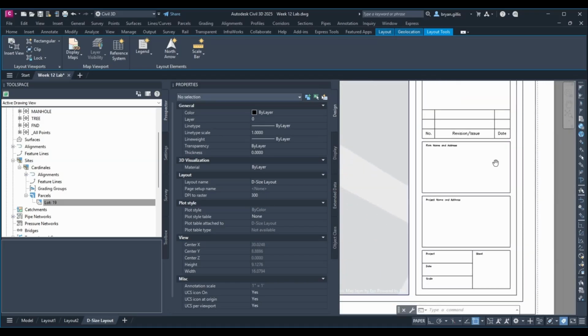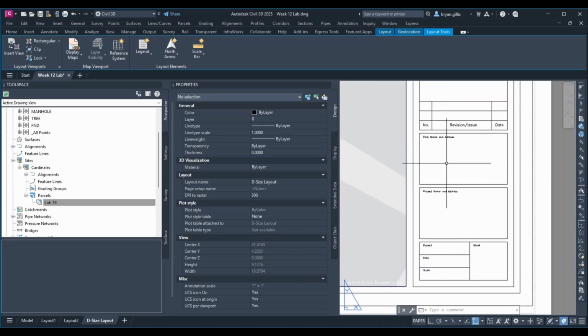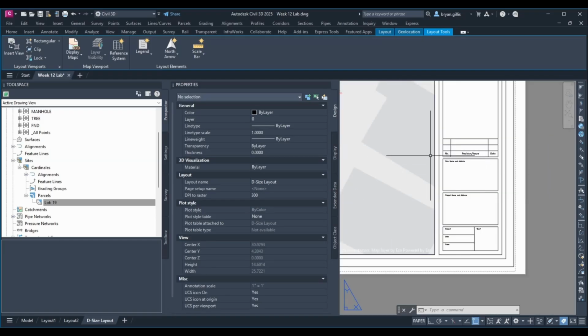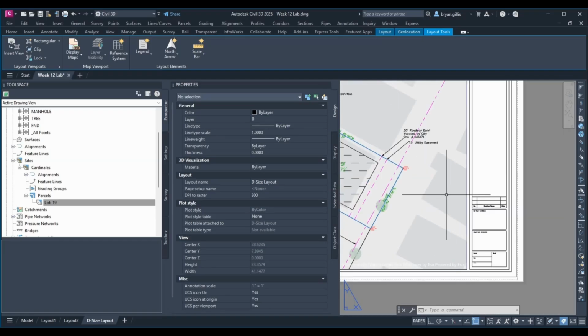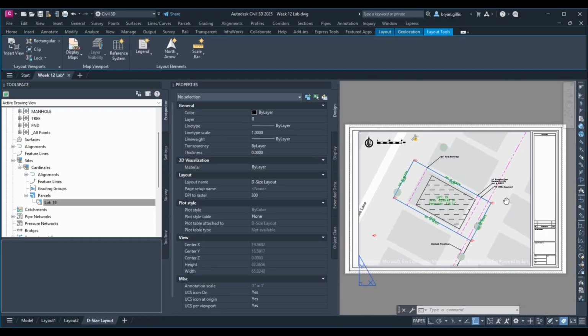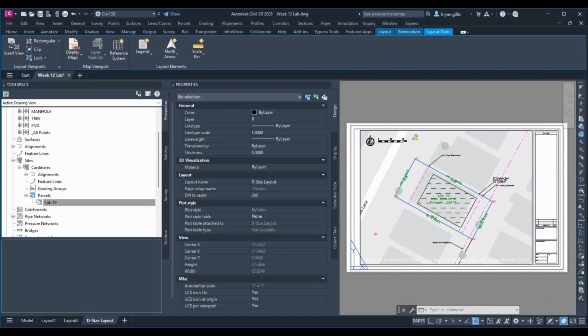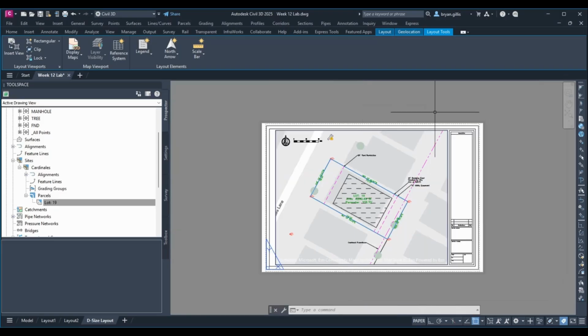I want y'all to come through. I need you to annotate and fill out your own title blocks. In Lecture 4, you should have all been quite familiar with specifically how to do that. If it doesn't have automated input areas for it, you're able to go into the Annotate tab and either do single or multi-line text. Go ahead and include that information, clean it up, line it up. Don't have a bunch of just random bits of text thrown all over your drawing.